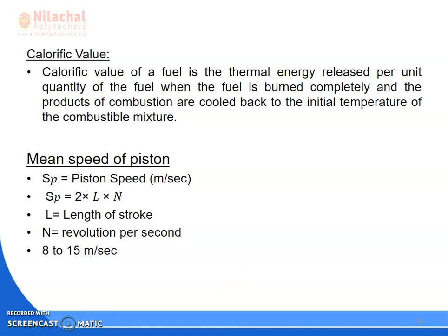Next we will discuss calorific value. What is calorific value? Calorific value is defined as the amount of thermal energy released by burning 1 kg of fuel. After the complete combustion of fuel, the thermal energy released is known as your calorific value. In the course of the third semester, we will discuss HCV, higher calorific value, and lower calorific value. If the products are cooled down to the initial temperature, that is known as your higher calorific value. If the products of combustion are exhausted, that is known as your lower calorific value.